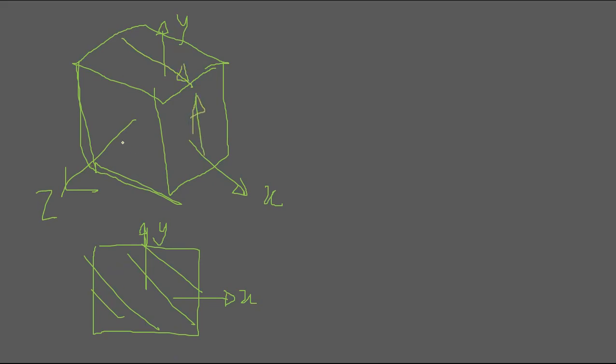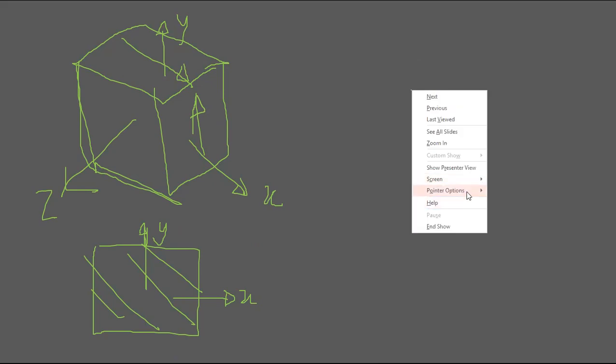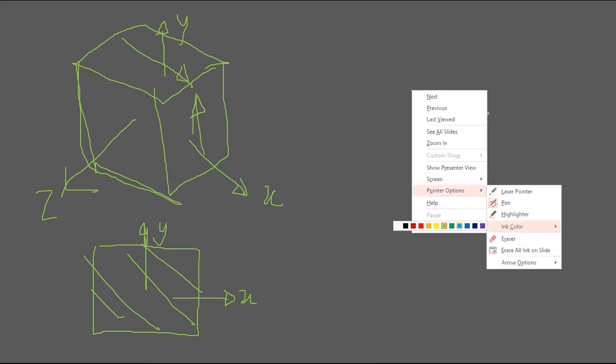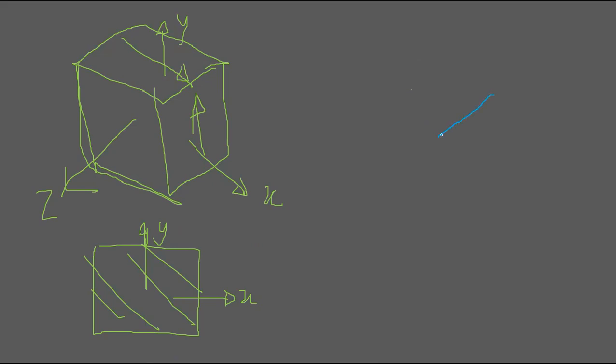So you need to rotate this xy plane then in clockwise direction. So it will be like this element finally. It is rotated, right? So that you will have sigma 1 in this plane, sigma 2 in this plane, and sigma 3 in this plane, right?